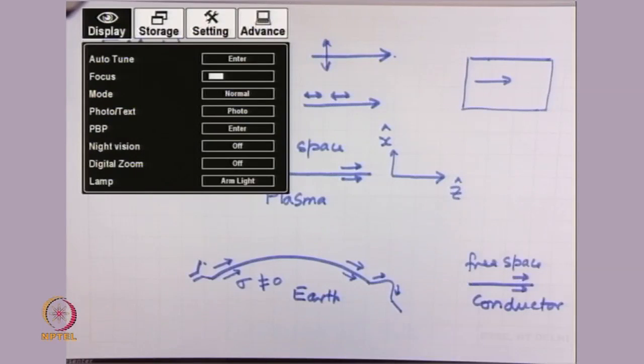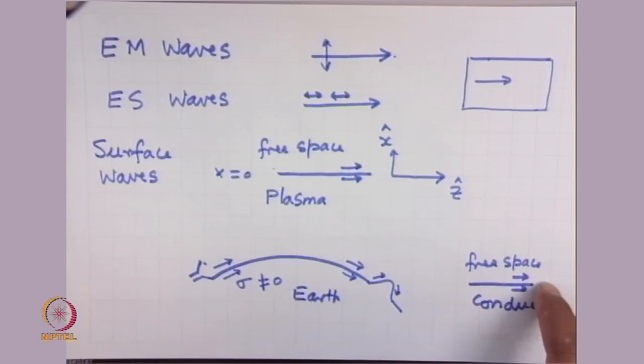They penetrate just very little, a fraction of a micron inside the conductor, and they extend a few microns in free space, and they are so much influenced by the presence of any contamination placed on the surface of the material that their propagation constant is influenced, and these can act as very good sensors. So there is a great advantage of employing these waves for sensor applications.